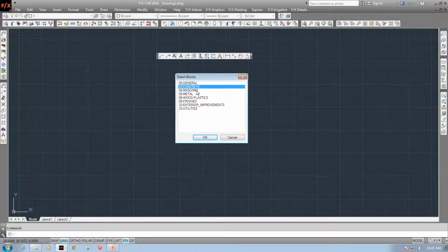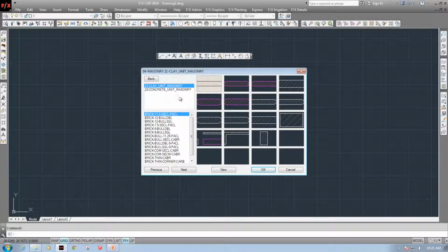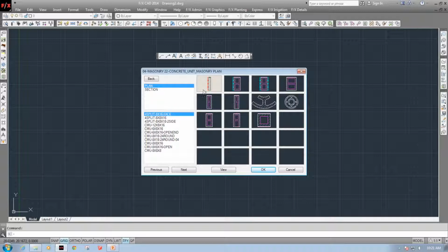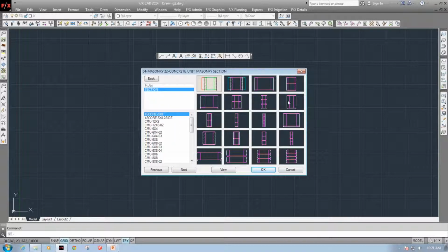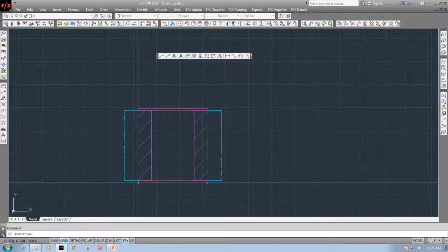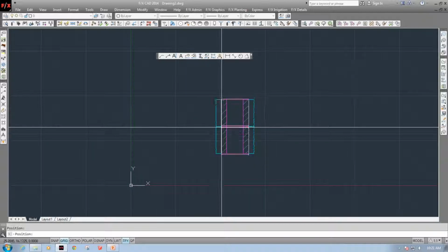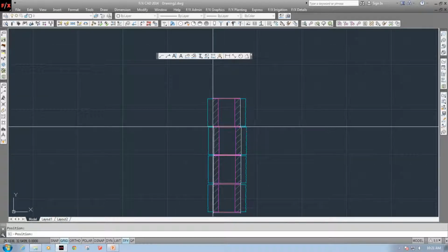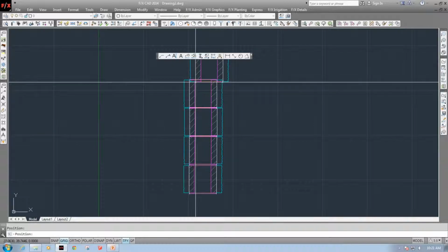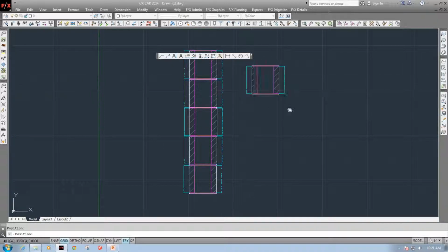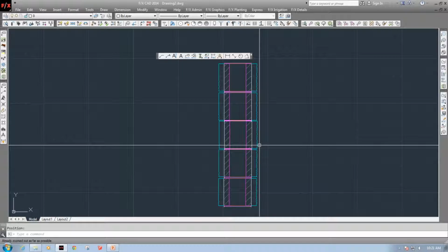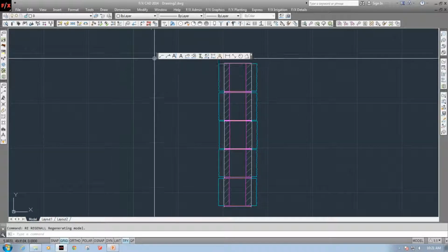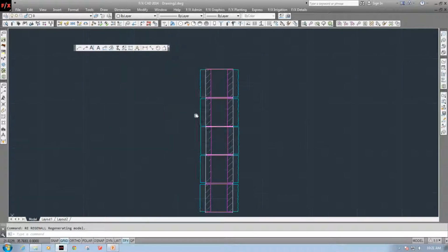So for example, if I wanted to create a detail of a masonry wall, I come in here, and this works very similar to our site where we have all these blocks, but I can come over to Section, and I can place a detail block. So I'm going to place him, and I'm just going to get real close. Like I said earlier, you would obviously spend a little bit better quality on your details than I'm doing just for the sake of rushing a presentation. And so now I have the fundamental components of my masonry wall.